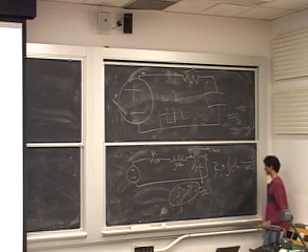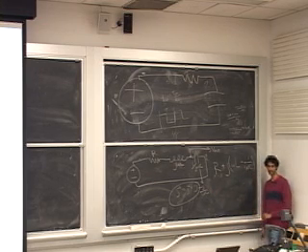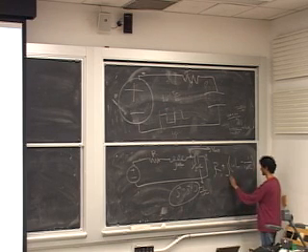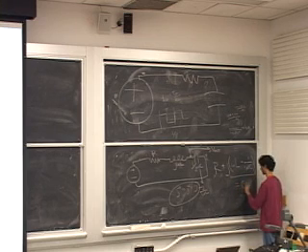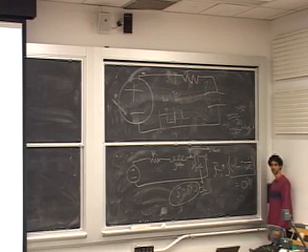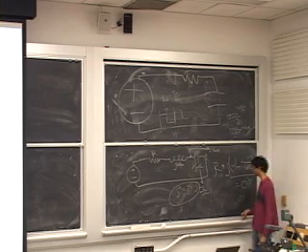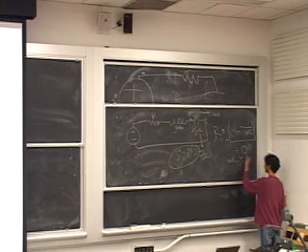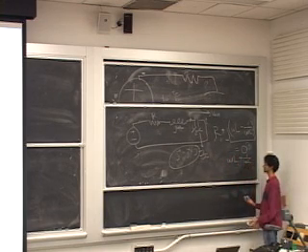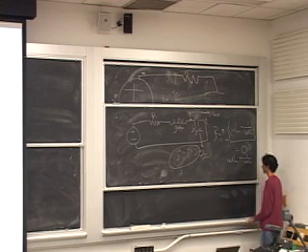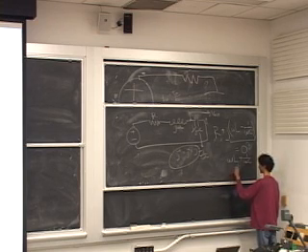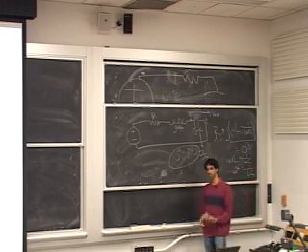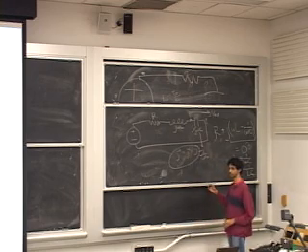So the first thing to note is I have a minus sign in my imaginary impedance. So when could I set this imaginary part to 0? Is this possible? They should equal each other. That's right. So when omega L equals 1 over omega C, I get 0. That's kind of neat. So when does that happen? We can say the frequency omega squared is 1 over LC. This gets into a property called resonance of a circuit, and I'll talk about that more next week.